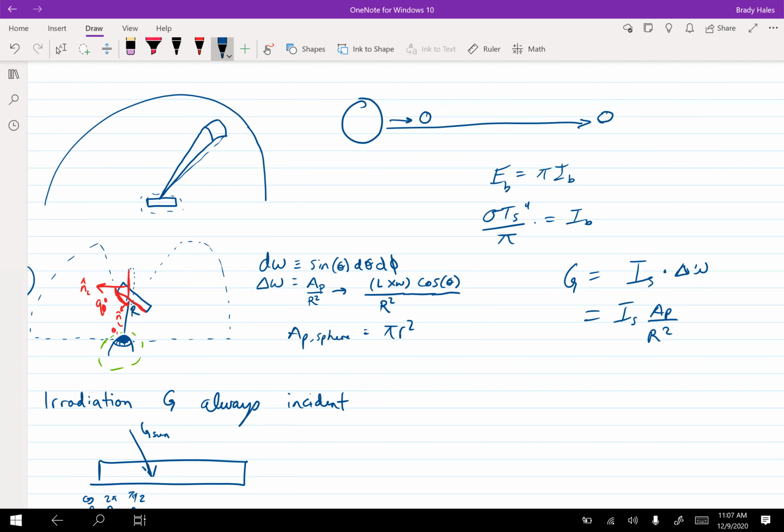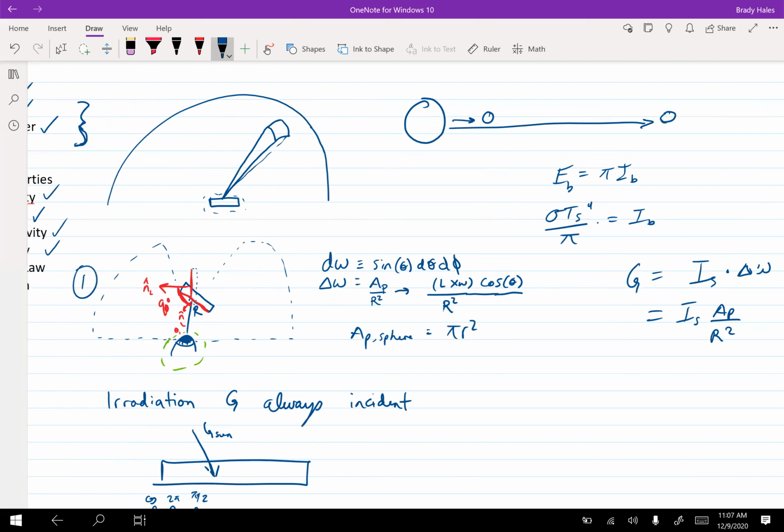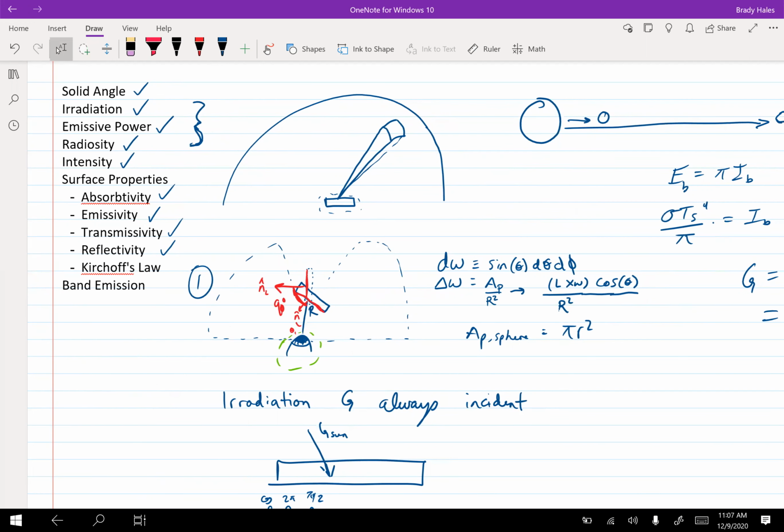And so that's why the G term, the incident irradiation, is much different between Mercury and Pluto, but the intensity is the same. Okay, so intensity is a conserved value, which is why it's used in all three of the G, J, and E triple integral definitions.